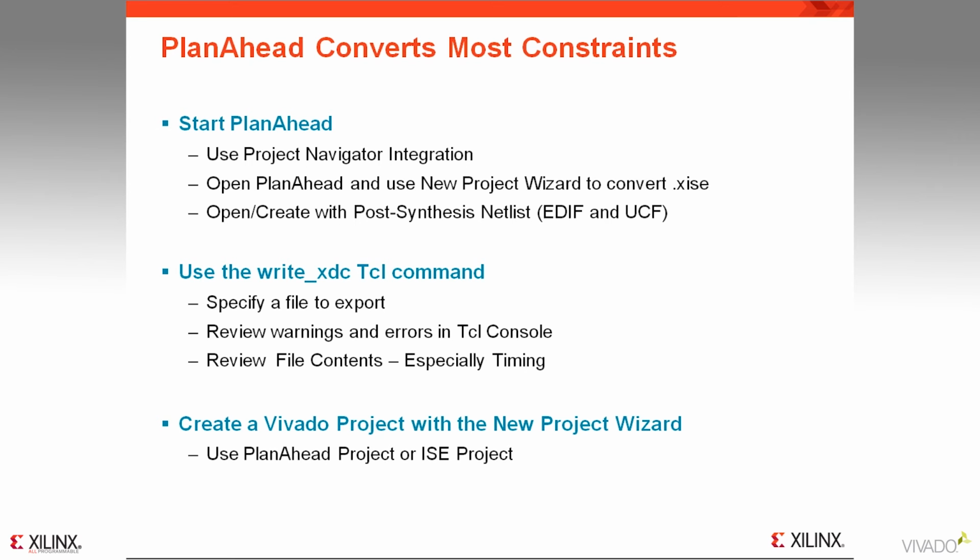We recommend you only use this XDC file as a reference to give you an idea of the equivalent constraints in XDC. The designer is the only person who can qualify the constraints provided to the tool, particularly the timing constraints. This is why we do not attempt to automatically convert UCF to XDC or support UCF directly in Vivado.